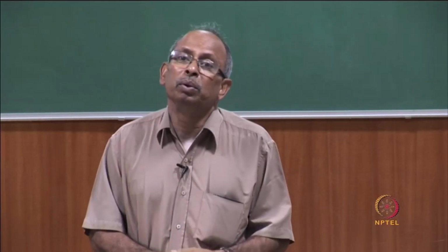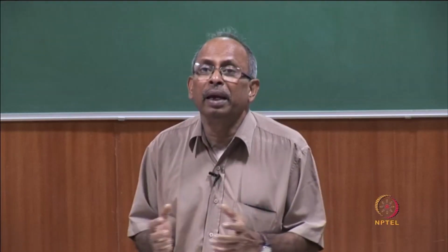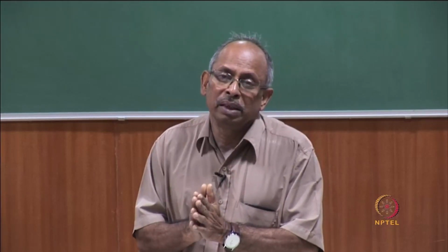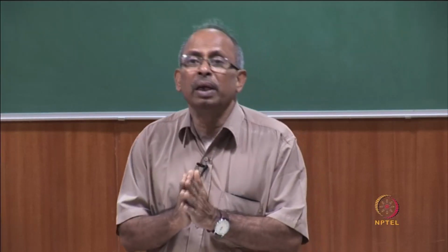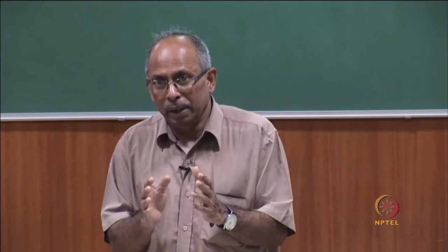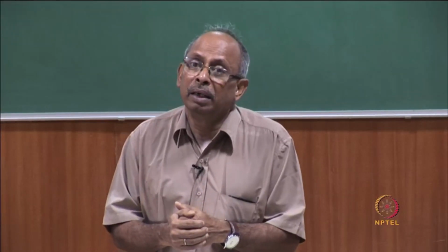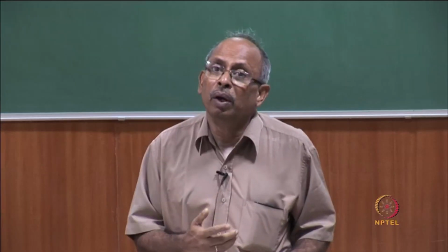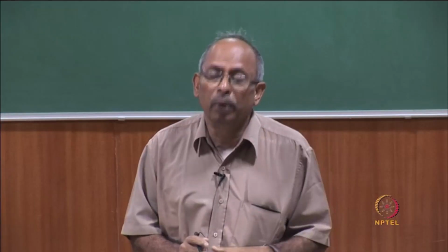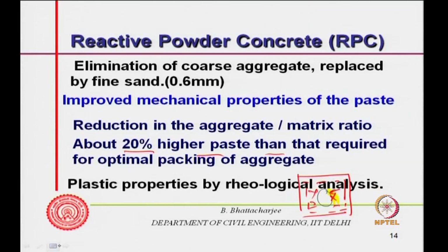That is largely because we want to bring in homogeneity and get rid of the interfacial shrinkage, because aggregates won't shrink, paste will shrink. But if the whole system is shrinking in bulk with a smaller quantity of aggregate inside, the interfacial discontinuity or cracking would be relatively less, right in the beginning before any load has been applied. So, use a higher amount of paste than required for optimal packing.